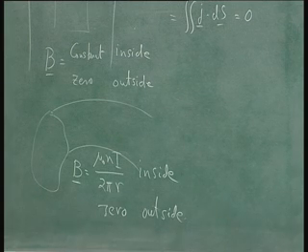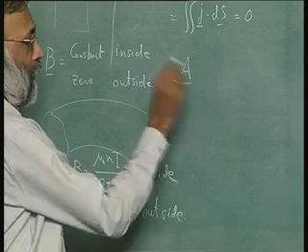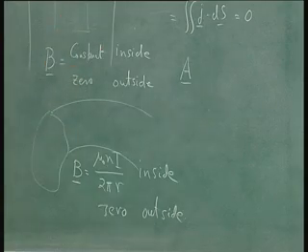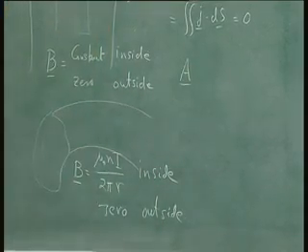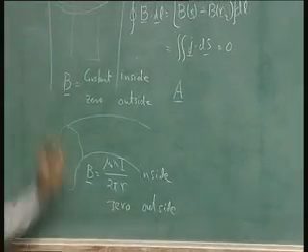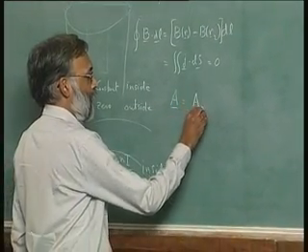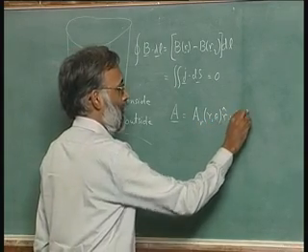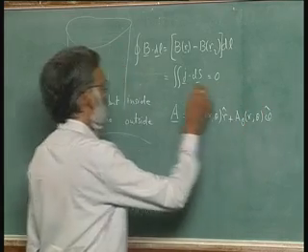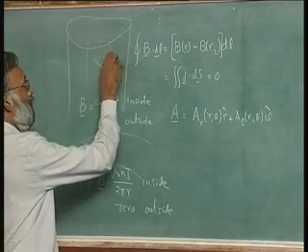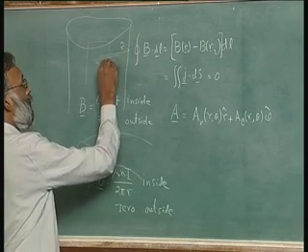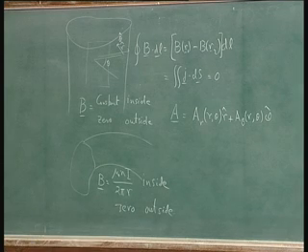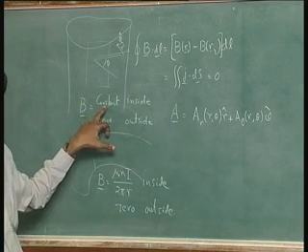We proved it by talking about the vector potential A and showing that if the vector potential A has certain symmetries, in this case vector potential A is not a function of z, and because the currents are all in r theta, we said that A is equal to A_r of r theta along the r direction plus A theta of r theta along the theta direction, where this is the r direction and this is the theta direction, polar coordinates. If you assume just this much, the rest follows.